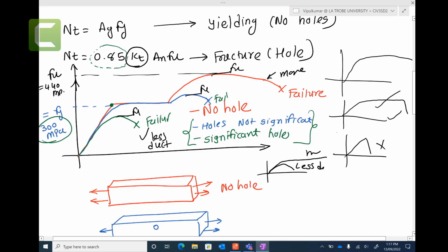Look at the red one. We now have a hole, nicely stretched, elongated, fully elongated, and then it will separate or break. It gives you plenty of warning before it fails. So if these buildings reach their failure mode, they should extend, and then they should fail.